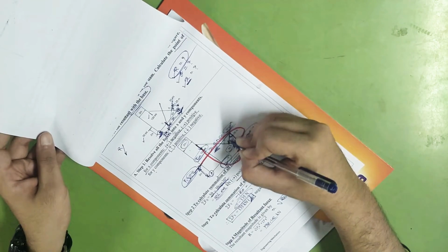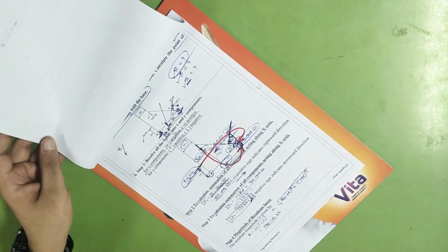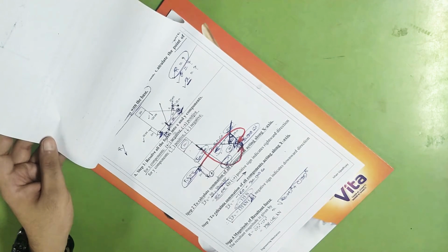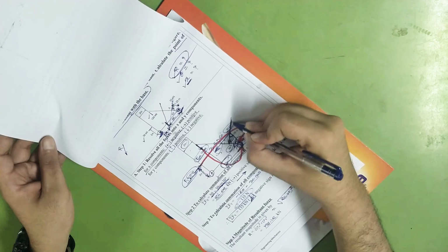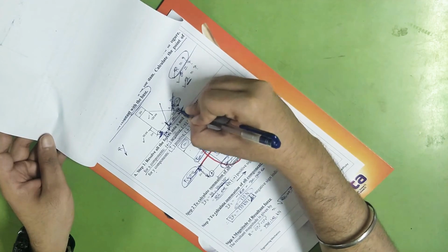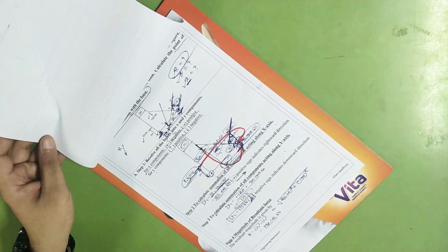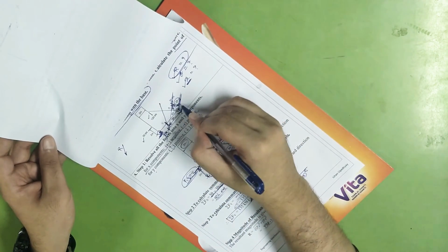Next we will go for this inclined force. Now one more important thing, we will not go for its components. Why? In the previous sum we were calculating moment for each component because we did not know the perpendicular direction of that inclined force. But in this case you know that this inclined force is at the given distance 1.25 meters with respect to point D. So a perpendicular distance is directly given to you, so no need to resolve it and calculate moment for individual components.